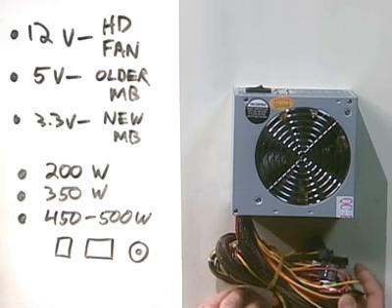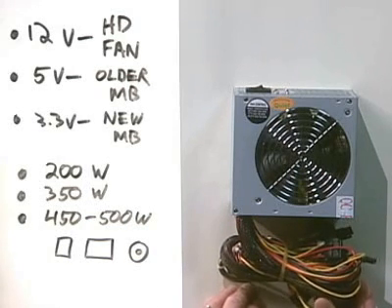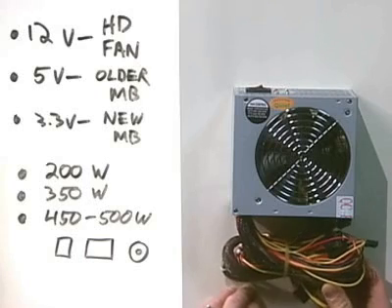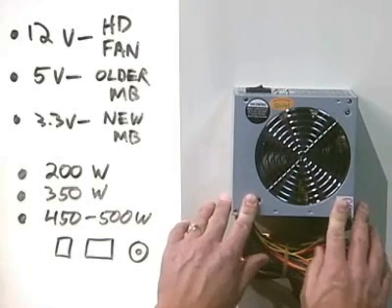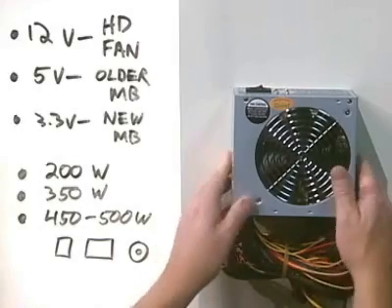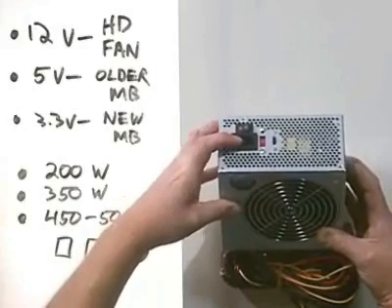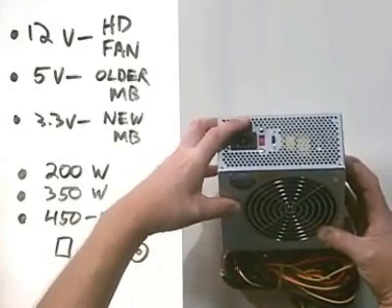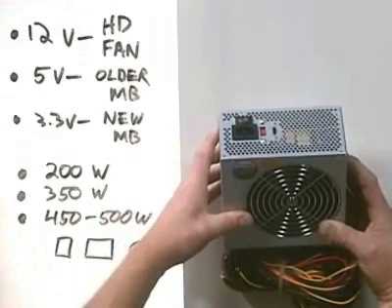Now, in addition to the roles that we've talked about so far, the power supply has one other role, and that is to provide soft power to the system. In older AT-style power supplies and motherboards and cases, there was a hard switch, kind of like this one right here, and it was used to break the wall current, the 110, 120 volt current. That's how the system was turned off and on.